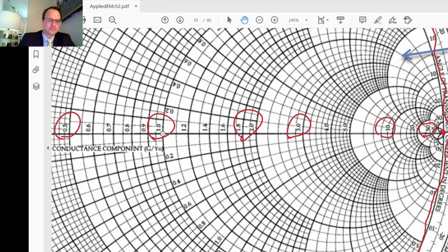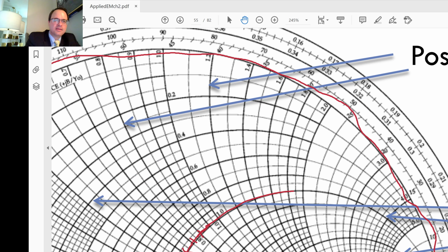Say we have an x of L of 0.9. This is a curve we're working with in this example of R sub L being equal to 1. So now we know our x of L is equal to 0.9. We look at the 0.9 x of L term, and this is the family of curves on the complex plane that defines x of L equal to 0.9. And so my load has 0.9 normalized reactance and 1 normalized resistance, and that point is defined right there.